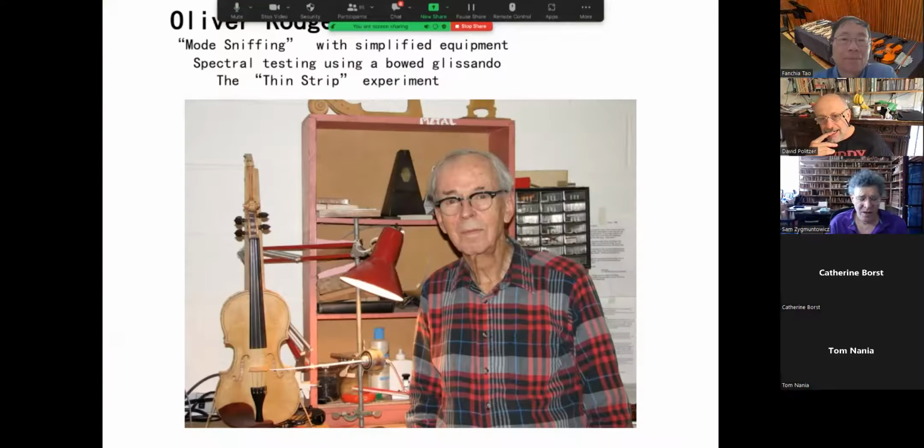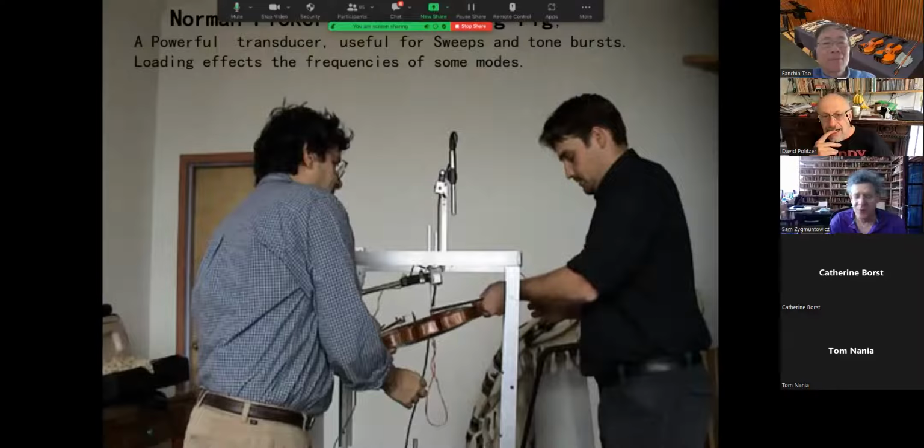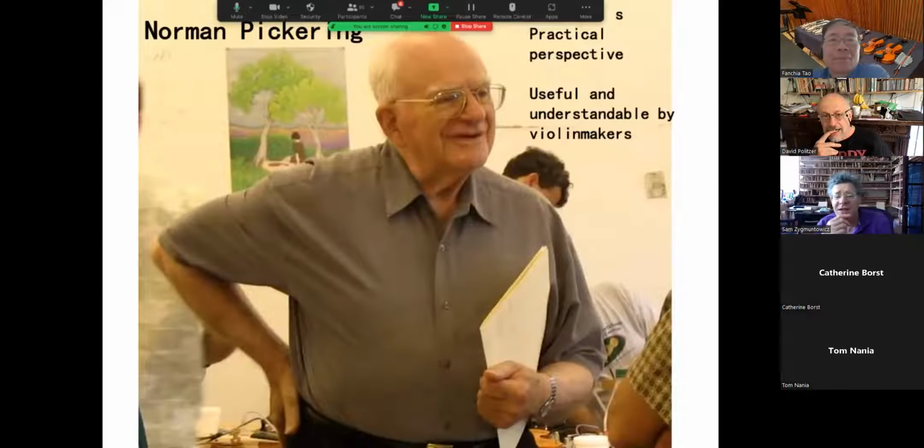I'll just go back to Norman for a second. One of the things he also did is he had a little metal ball on a spring that you could hold like a little mallet. You could put a signal into your violin and then probe around the surface, and when there was an area that was vibrating, it would rattle the ball. And it was a very, very analog form of modal analysis. That was trying to link what was coming out of the violin with the way the violin was moving.